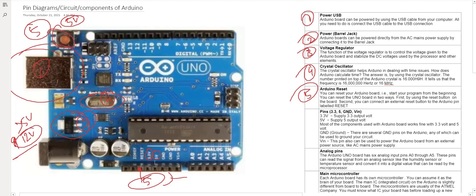After that there's a Vin pin. You can directly supply power from Vin, same as the barrel jack or the round jack. You can supply a range greater than 5 volt and up to 12 volt, and then the Arduino will convert it to 5 volt, supply here, and further convert it into 3.3 volt and supply here. And yes, there is one more ground here.